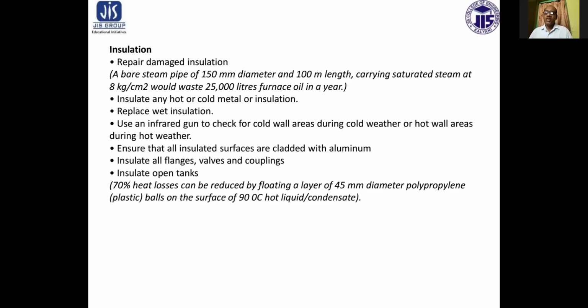Insulation, as we have discussed earlier also. Here a few tips are given. Repair damaged insulation. It is estimated that a bare steam pipe of 150 millimeter diameter and 100-meter length carrying saturated steam at 8 kg per centimeter square would waste 25,000 liters of furnace oil in a year.